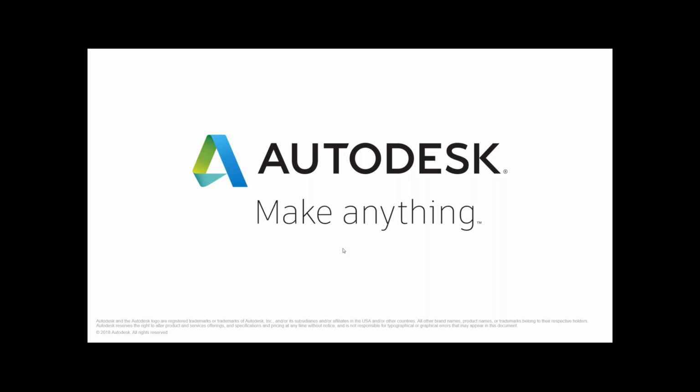Do you want to add anything to that, Vinod? Yeah, thanks, David. I think you covered most of it. Just to add, because I did testing recently with Plant files on AutoCAD Architecture and MEP. As long as the model is simple, Architecture and MEP have the IFC translators, which allow you to import them and save it as an AutoCAD native DWG. Then you can bring it in as an external reference and then generate it in your Plant.